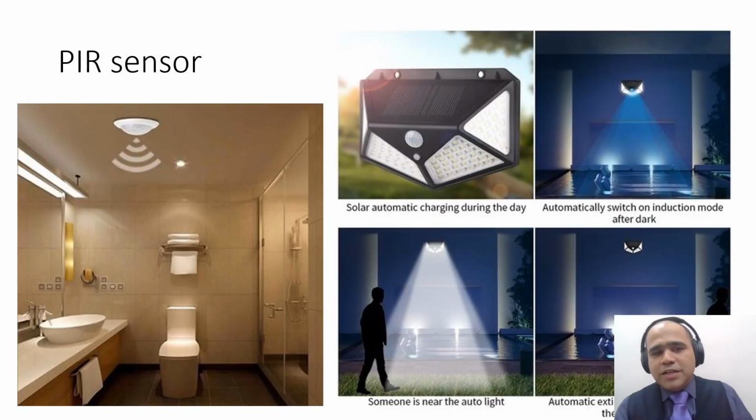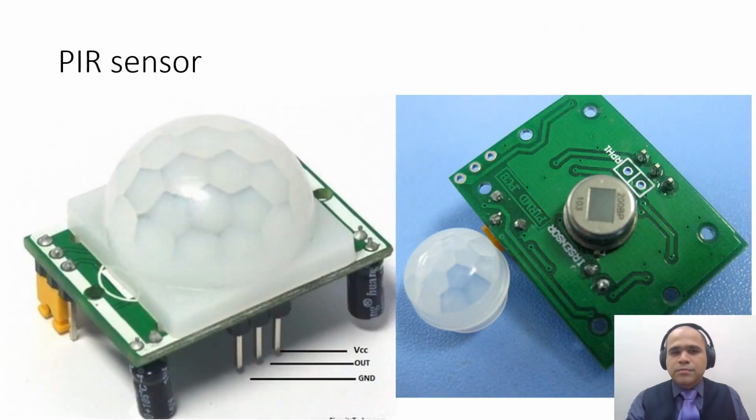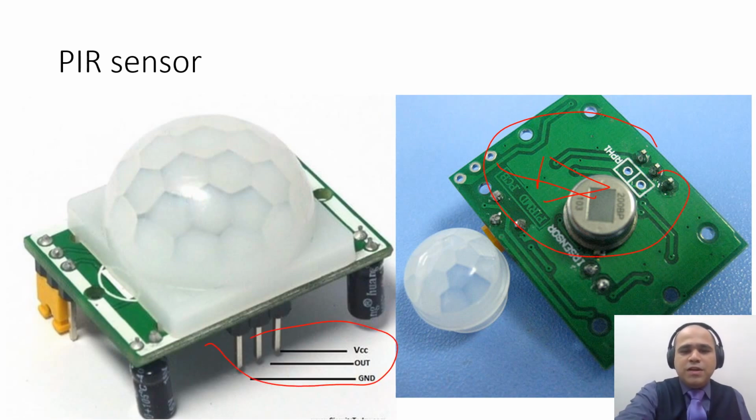Now, these are the magical sensors that, once they came out into the market, made light automatically start when you entered a room or anybody's garden. That happens because of a special sensor called a PIR sensor or PIR module. A PIR module comprises the PIR sensor itself and a backside amplifier circuit, and the output is typically VCC, ground, and a 0 to 5 volt TTL signal.